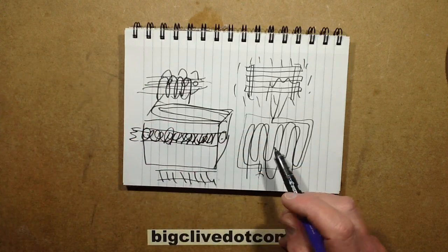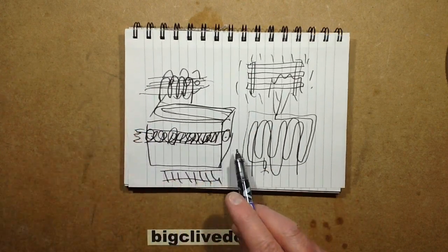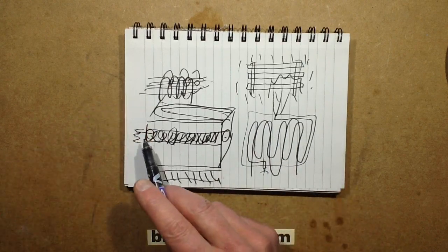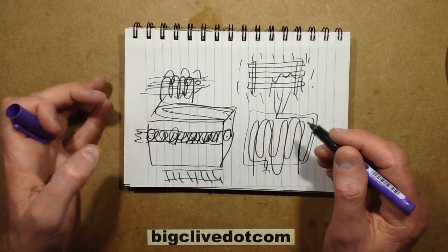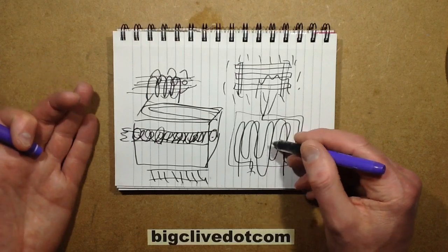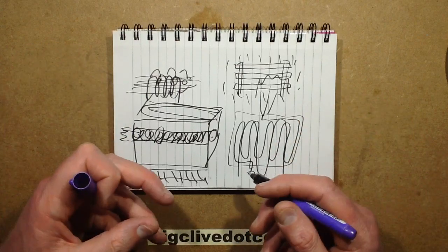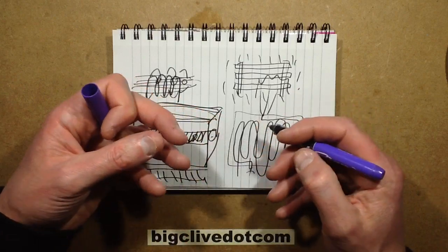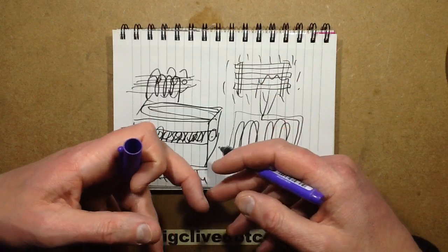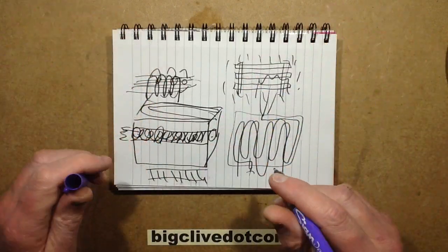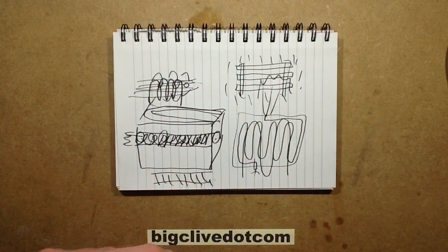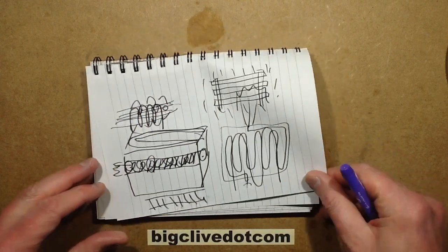It's a lot cheaper and simpler to make than the copper tube one, but it's not as efficient. It doesn't create as good a fog, and with the shorter path, it's more likely to blow out liquid. This is the case if you've got too much water in the water to glycol ratio: when it's pumped in, you end up with too much pressure. It tends to sputter and blow droplets of liquid out the end. Sometimes you need a fairly accurate balance with smoke machines. So that's the principle of the atomization.